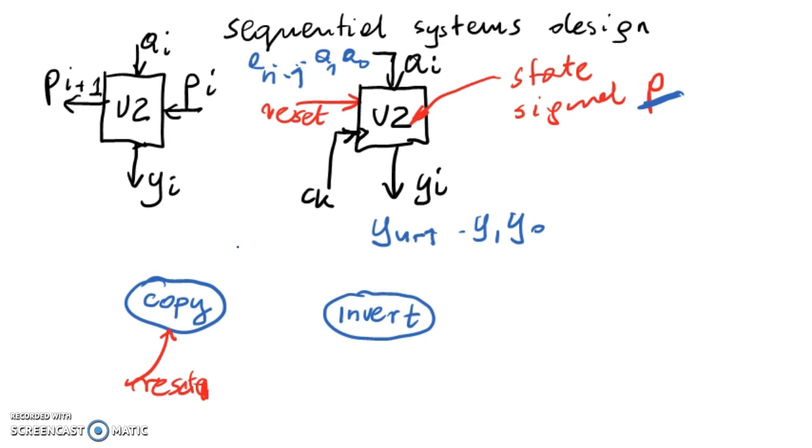Let's do this in the convention of a Mealy machine. You've got the states inside the circles, and the output signal Y will be presented aside of the arrows. When you move from copy to invert, when there is the first one, it switches to the invert state, and there is no return arrow back to the copy state.